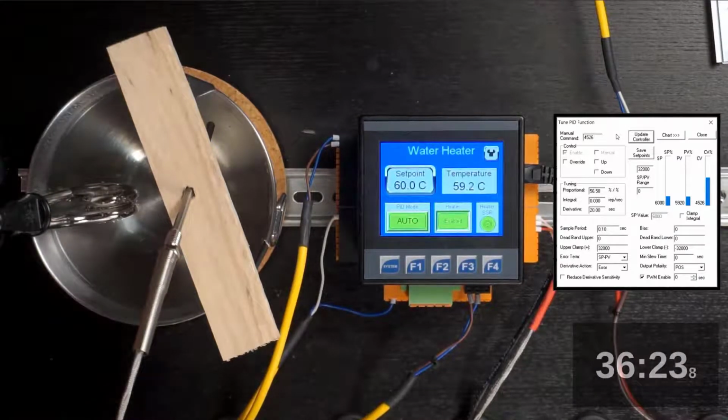Okay, now normally I would let this run a little while longer, really on all these trials, frankly. But for the purposes of demonstration, I think I've come to the conclusion that these changes to the derivative have not really made a difference in the positive direction. So I'm going to go back to the original coefficient value after the auto tune, and I would imagine we'll settle back in at about plus or minus 0.7 or so.